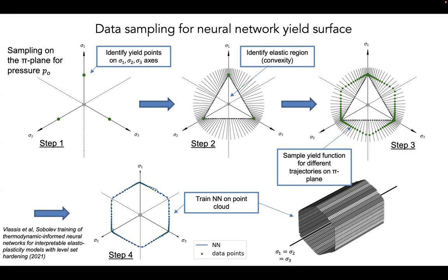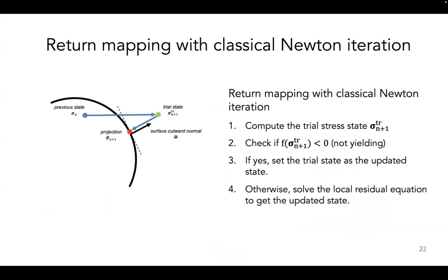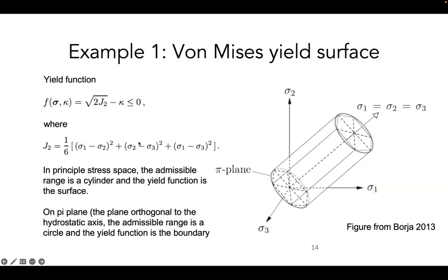So I'm going to write a function, and the yield surface can be as simple as this. Now this one has values. I'm going to learn that, and the yield surface is only a scalar, so I can do it with any supervised learning. The problem is that this particular example is more extreme. I only give you the value of J2 and the pressure when F equal to 0. I don't give you any other data. Can you write the function?